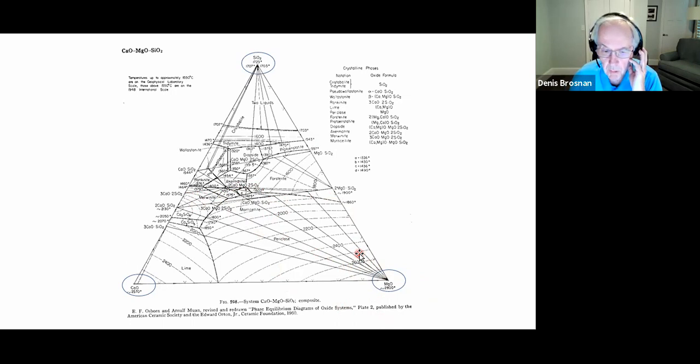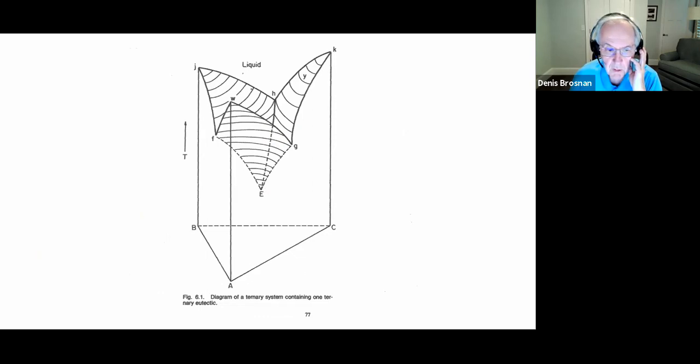But now we have 2 fluxes present with respect to sintering. These are silica and lime. So we're going to look at this. And even though this diagram has a lot of compatibility triangles and a lot of eutectics and peritectics in it, we're going to simplify it. So we're looking down at the liquidus surface. The next diagram is a perspective drawing from Bergeron and Risbud.